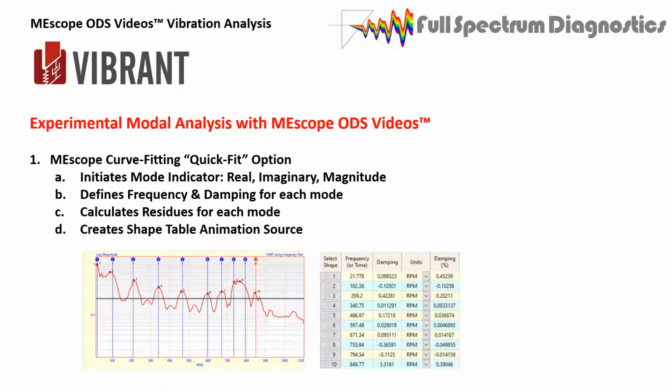Modal analysis has data that usually needs to be curve fit. My little plate that I showed you, second bending, third bending, rigid body modes, all that stuff, I never curve fit, but this truss structure I did. The idea here is to make sure that you're actually zeroing in on mode shapes instead of something that's not, an amplitude, background noise, what have you.